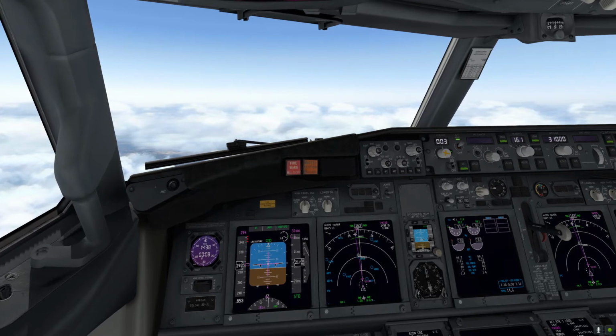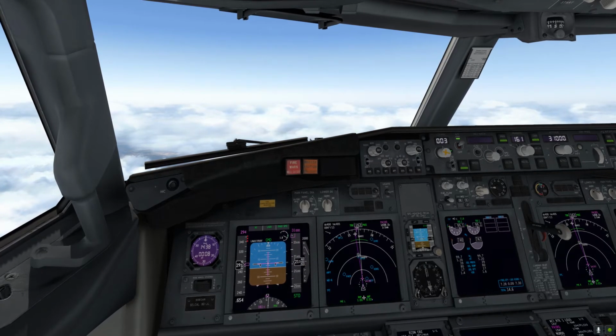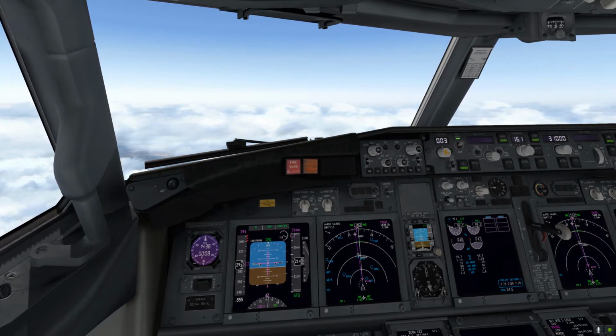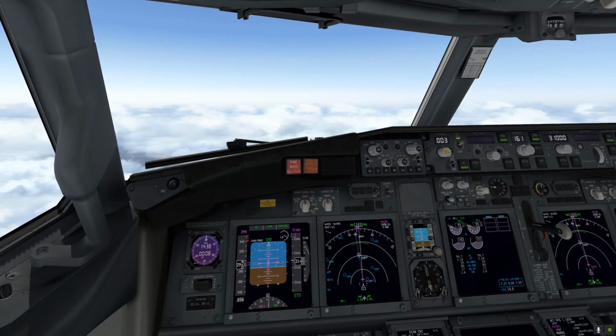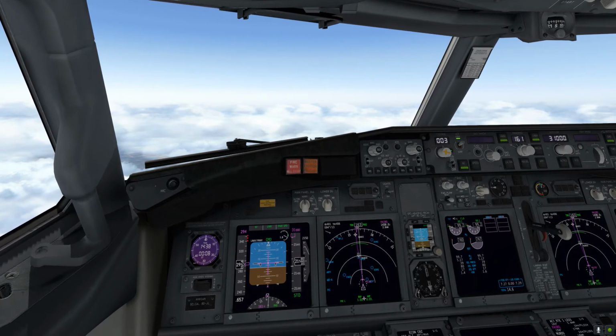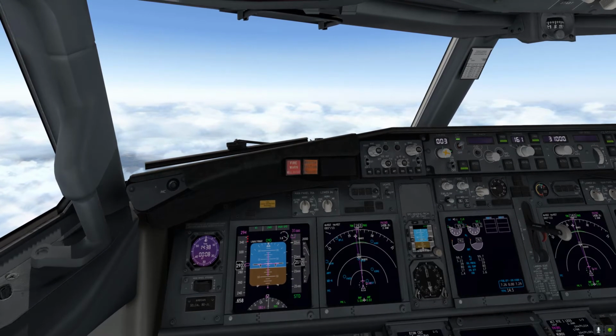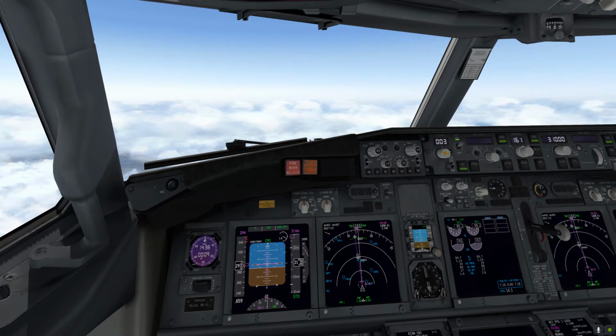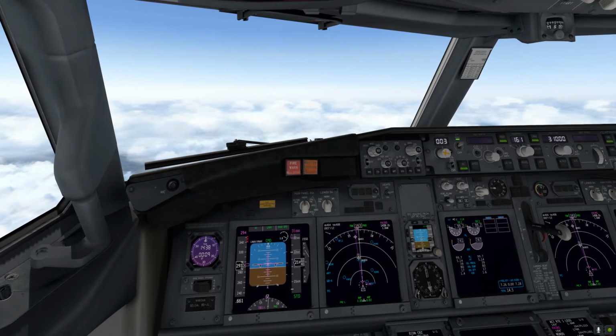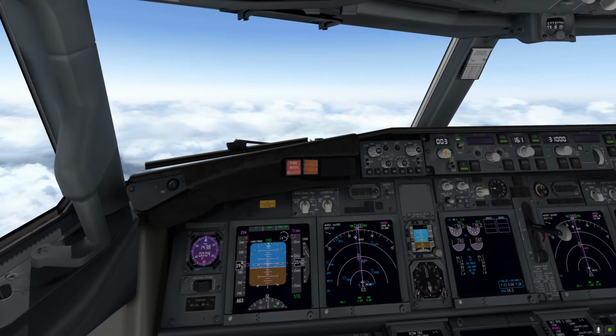Yeah, it says still wind 130 degrees, 17, gusting 25, 8 miles visibility, light rain, scattered 1900, broken 2700, overcast 3800, 27 degrees, altimeter 2979, and parallel approaches in use.